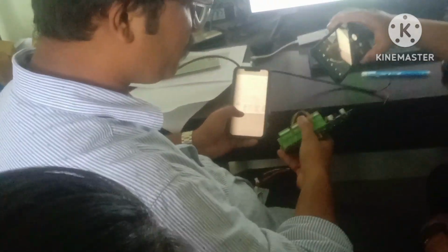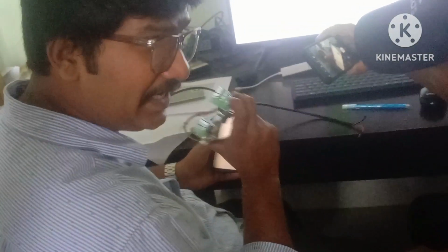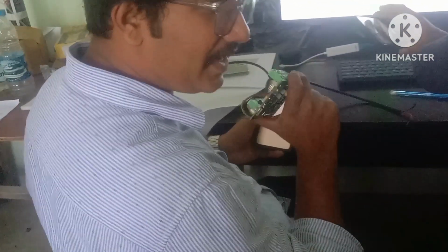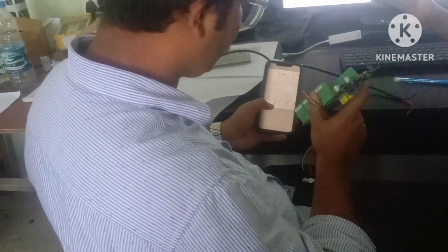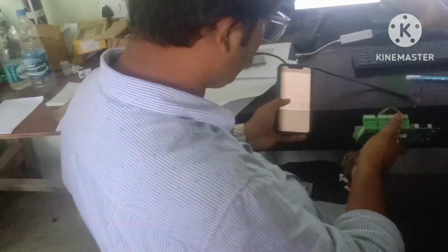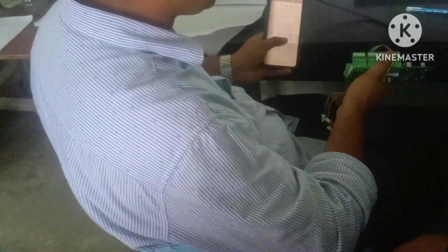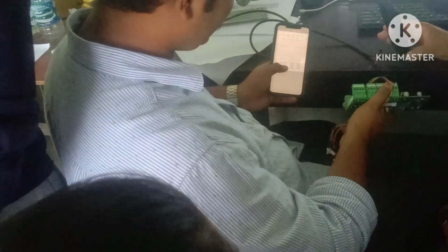We have two types of control. This works individually also, it has manual mode, so you can set any point from the thermostat and it will work on its own. Therefore it has two auto manual: one for changeover from the panel and one for changeover command to AHU on.